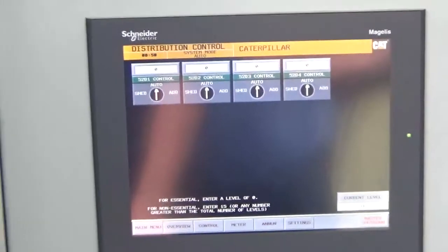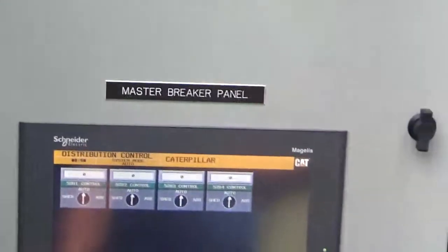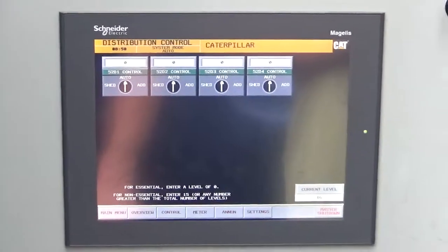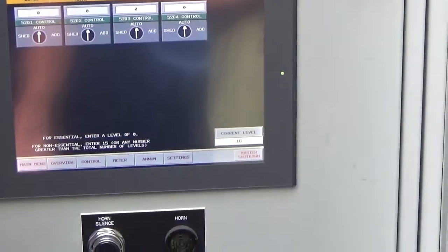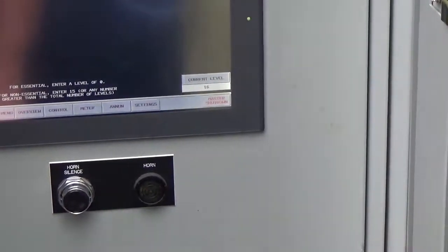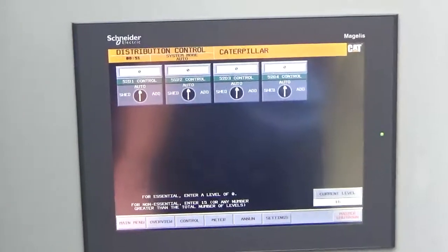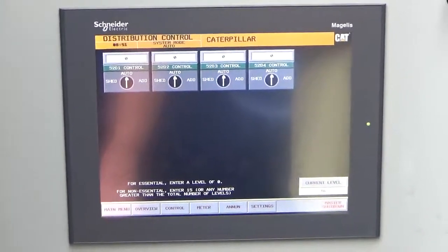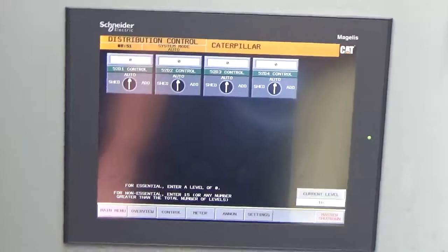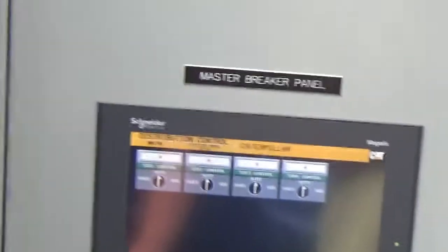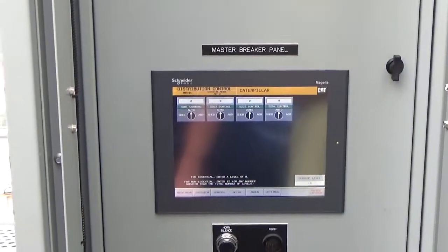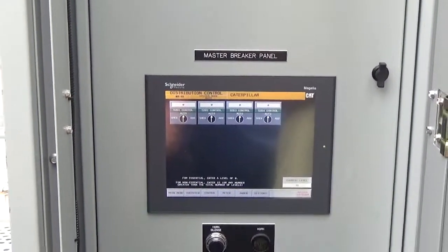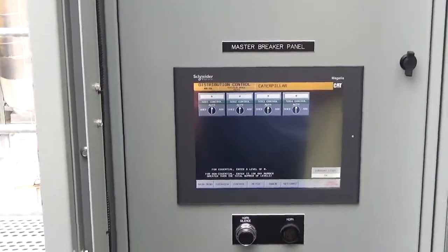So whatever you do in here, we can technically do at the shop? Yes. We don't physically have to be here? No. You can do everything from the shop, down where you have this other screen. Now you've got to remember though, what you change here changes down there, and what you change down there changes up here. They mirror each other. Now I do notice, when we got that pre-alarm, we reset it here, cleared it, acknowledged it, but our other 2 annunciator panels, not the full-size panel, the little LED annunciators, weren't cleared. We had to actually go to those. Correct. That is independent of the switchgear.